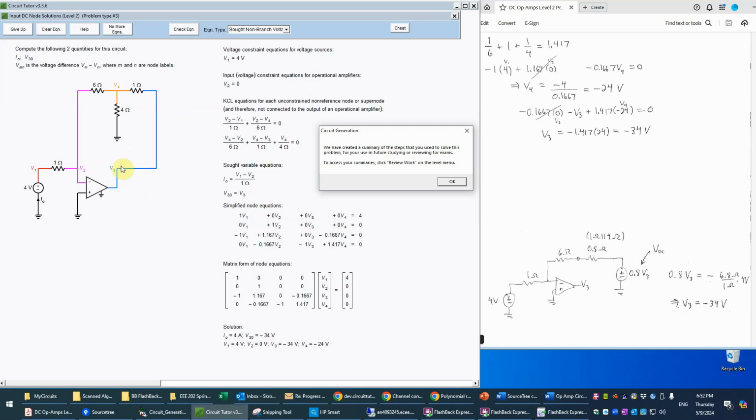So in other words, if we think of this as being the voltage V3, let's draw our terminals here and also at ground for the rest of the circuit. So basically we represent this part of the circuit by a voltage source in series with a resistance. Okay? So the first question is, what is that Thevenin equivalent resistance?